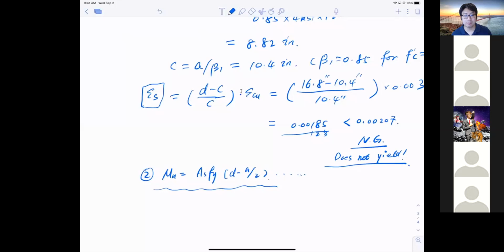I still don't understand why you want it to yield either. Okay, so if we have a beam and the steel yields, yielding steel means the steel will go into a permanent deformation while holding its strength, right? That means your structure will deform gracefully.